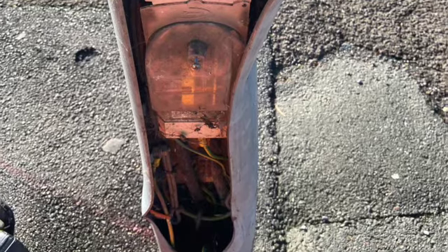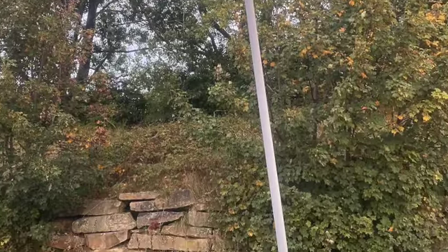It's a bit of a frustration for us sometimes when we go to complete a non-destructive test and already there's obvious damage to the column, so the base compartment's dented or the column's leaning, because those really will get filtered out at the start of the process and they won't be suitable for the attachment. You'd need to replace the column. So just a simple site survey to determine visually clean columns, and also potentially columns that don't support existing attachments, you've then got the very best chance of getting your attachment approved.